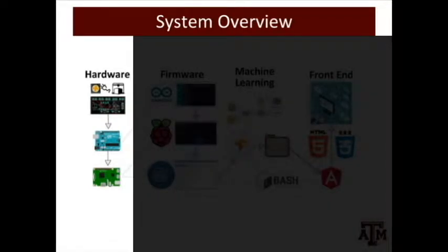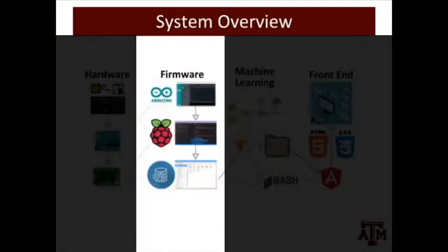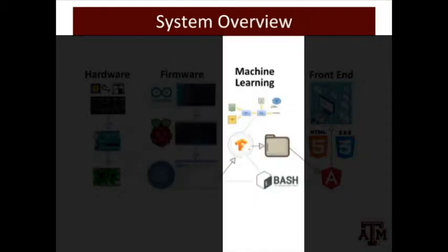The hardware, used most importantly for the physical collection of the incoming acoustic data, and also all other necessary peripherals for the device execution. The data collected is then retrieved and processed by the firmware, executing operations such as Fourier transforms and noise cancellation for increased performance. The processed data is then analyzed by the machine learning, which will conclude whether the target fan is healthy or in risk of potential failure.